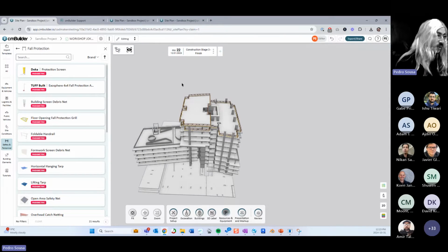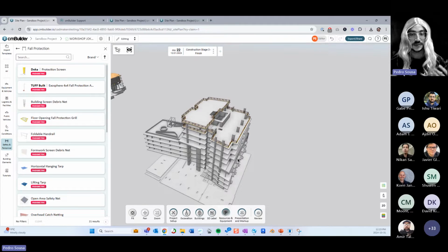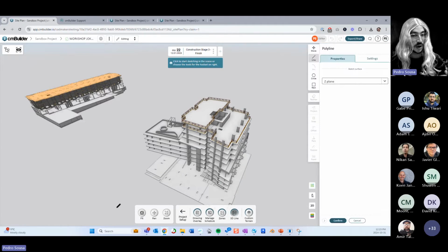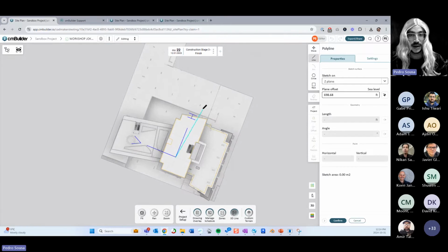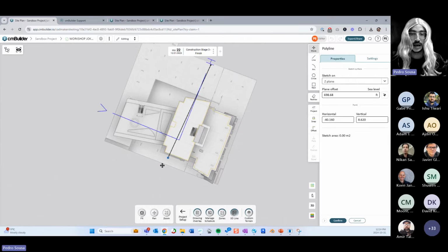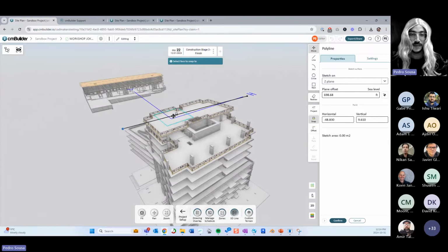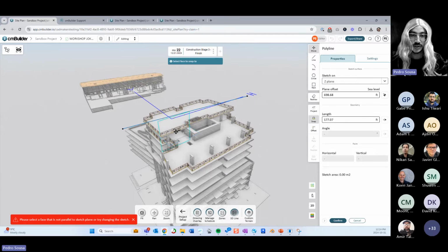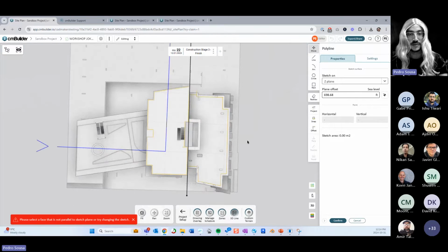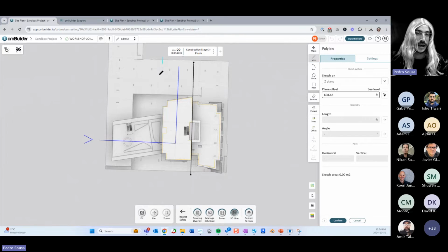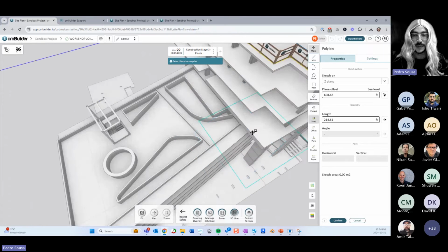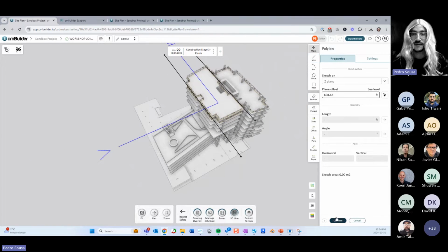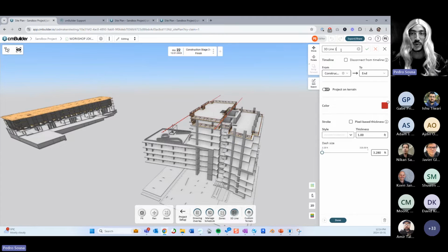So until we post that, one thing that I would suggest is for you to create a template of your splits using a normal 3D line. So you create a template that you're going to split this way, the same way that I did before over there. So I can snap this to this face. And that's going to be my template for this split, but I also want to create a template for the amenity levels. I can do the same thing over here and snap this. And I have these 3D lines. Their name should be something like template split, right?